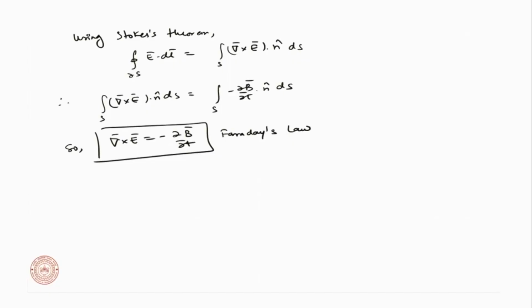So, if the magnetic field strength is varying by time in any way, whether due to the motion of a loop, whether due to the motion of a plane, or whether due to some electromagnet which can induce a time varying magnetic field, our electric field will be induced, and that will create the current to flow through the given loop. Okay.